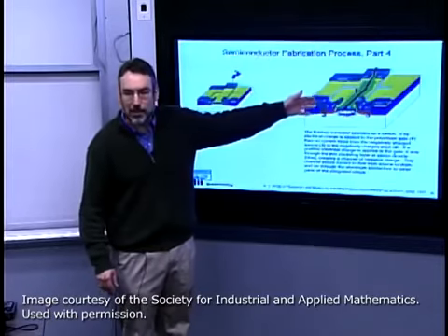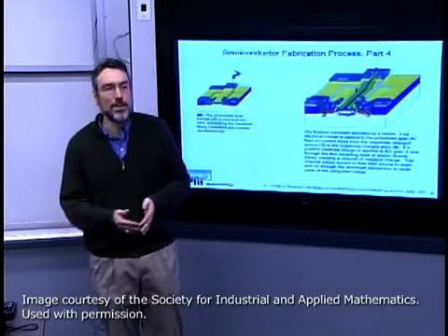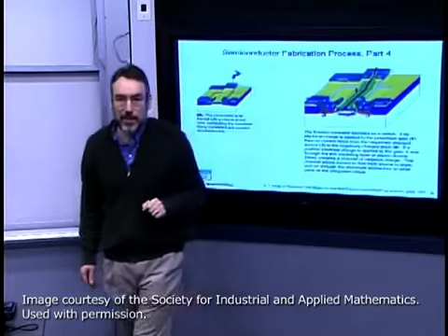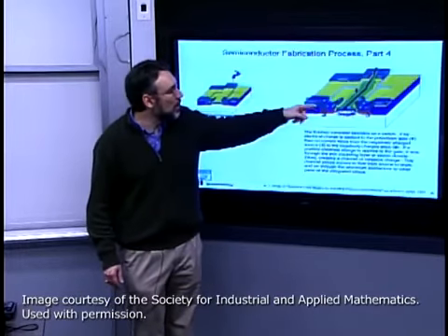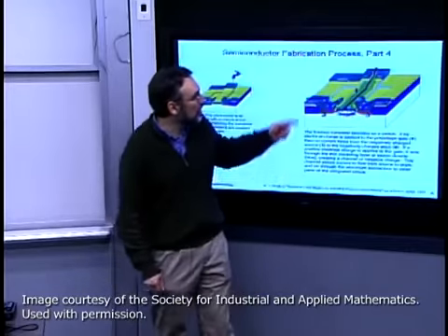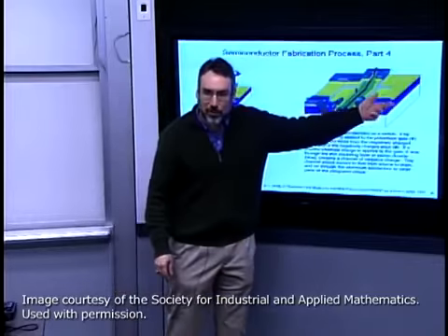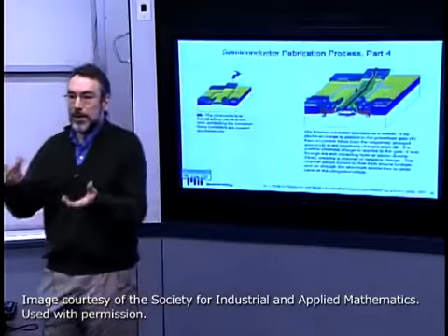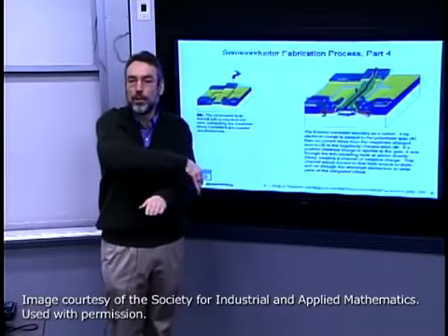We now need to also electrically interconnect all of those devices. And there's a whole additional sequence of process steps that are used to build multiple levels of metal contact. But conceptually, they're very similar to those that we've seen so far. Here I've got access to this individual transistor. Clearly, laterally, I can have neighboring transistors that I've wired together with the patterned aluminum. When you get a certain number of transistors, it becomes very hard to have just one level of wiring. You need to be able to have a wire that goes over another wire.